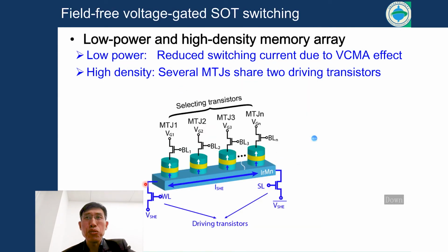And then we can propose this structure to overcome the problem of three terminals. We can see that we share this SOT channel, because it passes through the bottom of the devices. In this case, we can consider it a 2-point-X terminal, could be 2.1 terminals if we put many magnetic tunnel junctions on the AFM electrodes.